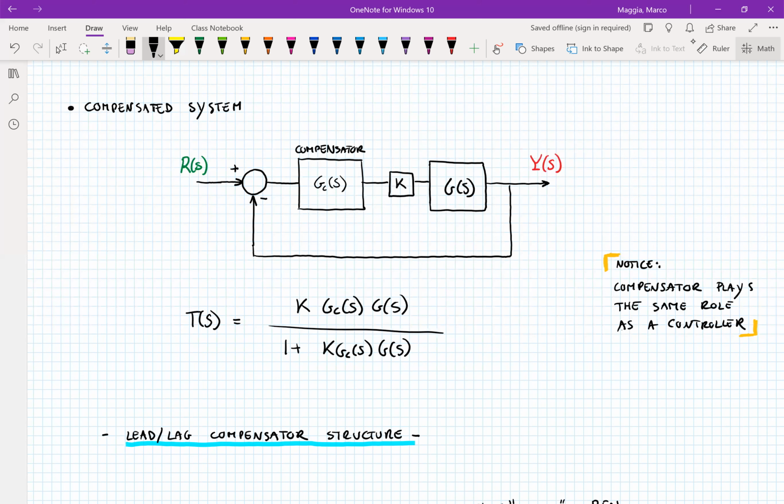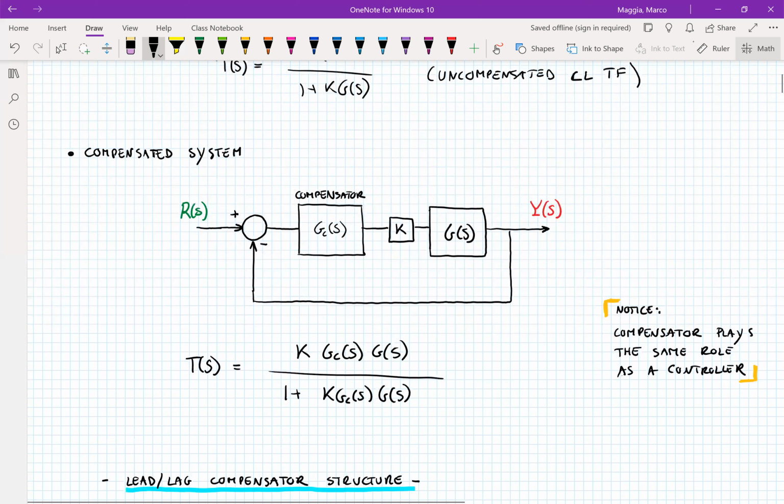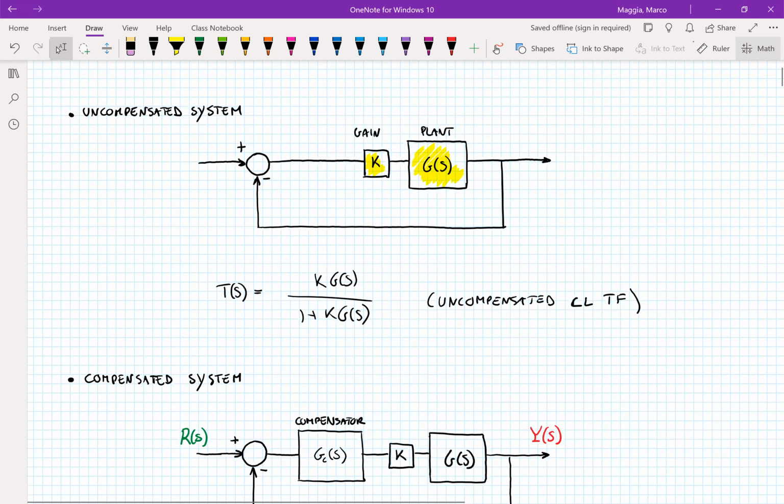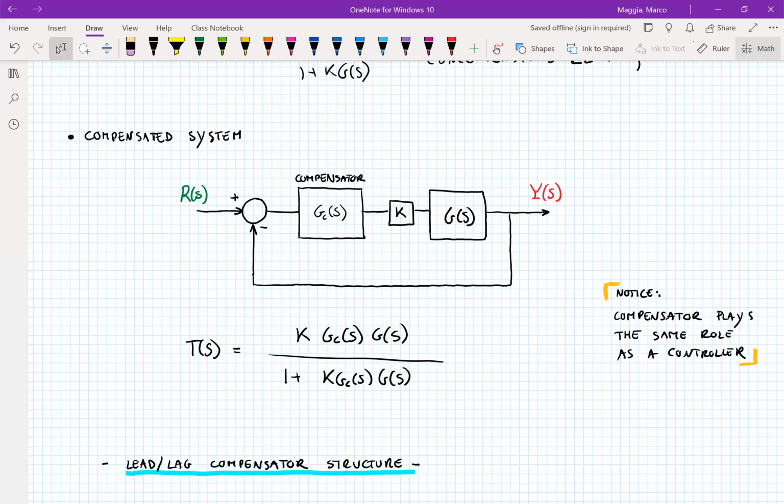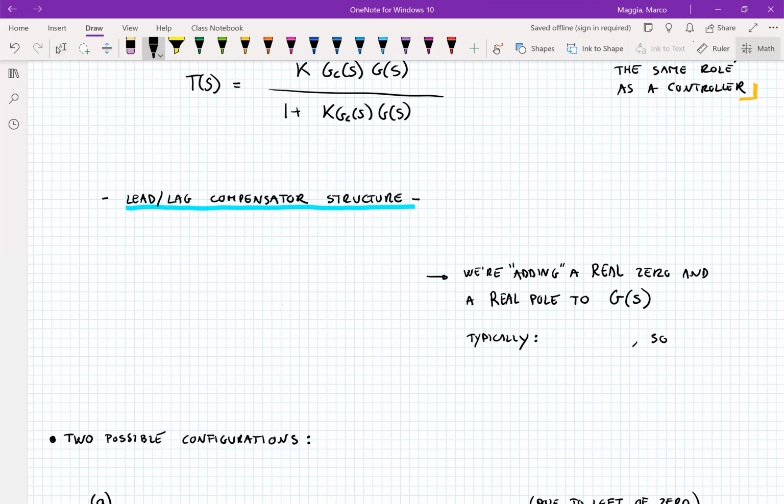All right. So now what is the nature of the compensator? Let's say that we don't really care now what G(s) looks like. We want to focus on the structure of the compensator. So phase lead or phase lag compensators have both the same structure, and this is the following. In the S domain, they have a transfer function that is a fraction, and at the numerator, we have a first degree polynomial, s plus sigma z, and at the denominator, we have s plus sigma p.